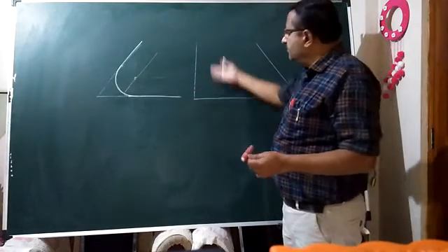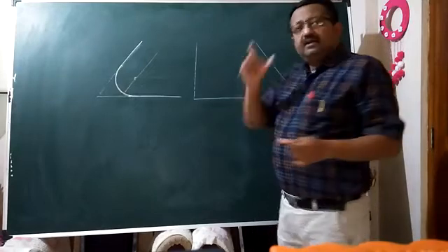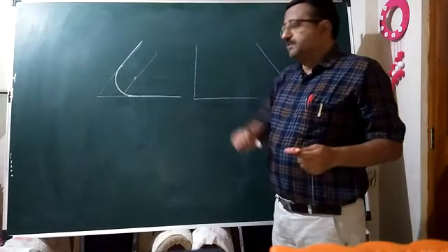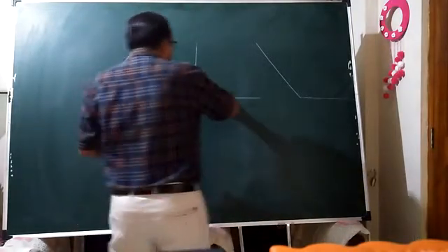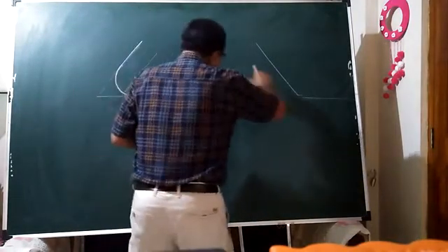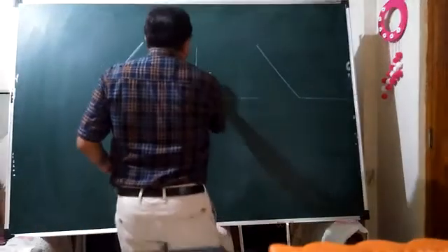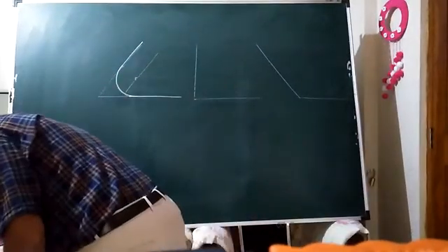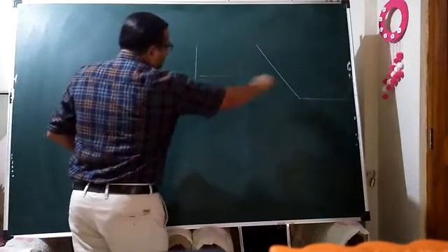Now suppose we change the radius. Pick now a 30 mm radius. These two right angle lines we have to connect by a curvature carrying 30 mm radius. Now the same procedure. Hold the scale here first of all. Get a 30 mm departed horizontal line in this way. So that 30 mm departed line I have got in this way, 30 mm from this line.